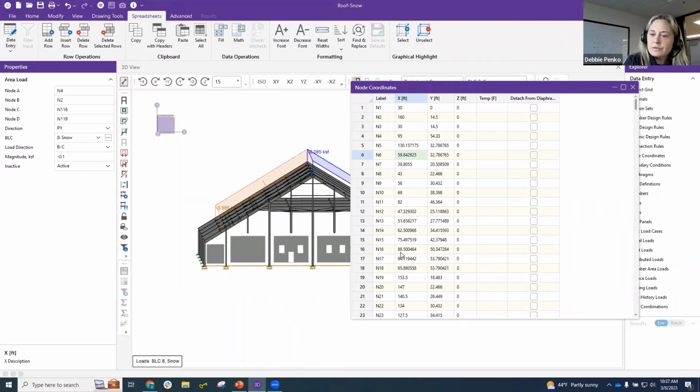When you draw it yourself in RISA-3D, you probably aren't going to get these crazy different length numbers. But if you import it maybe from another CAD product, potentially you do get these very long numbers. It's normally fine, but every once in a while it can be a problem where things don't line up properly and you just need to clean it up.